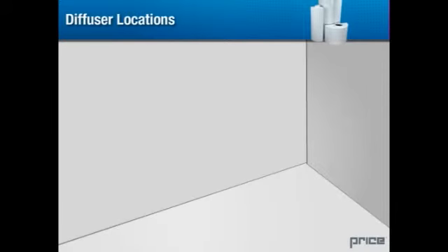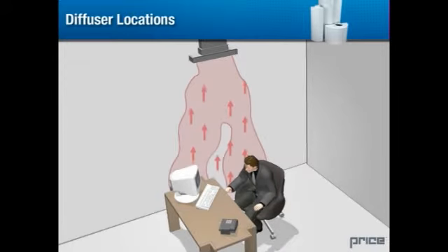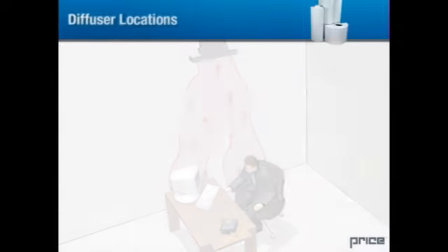For the air return outlets, it's essential that they be placed at high levels, either on the wall or in the ceiling. The same model types for mixing systems would apply to displacement systems. Locating the return air outlets above strong heat sources will ensure the efficient removal of the heat and contaminants generated by the thermal plume.